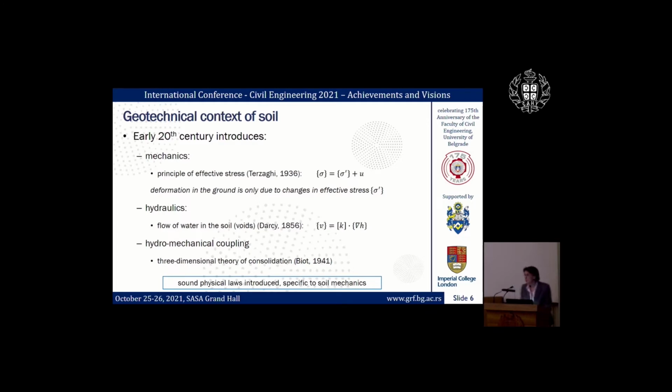And then Terzaghi also combined the well-established Darcy's law of flow of water in a medium, realizing that essentially this is governed by the permeability of the soil, so the size of that void space, as well as the pressure gradients, here expressed as the head H.